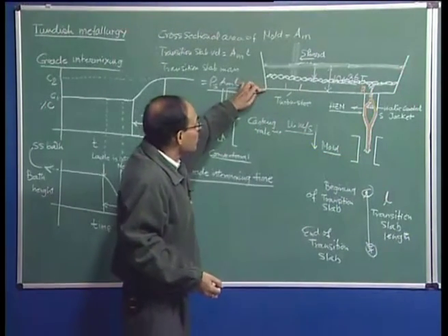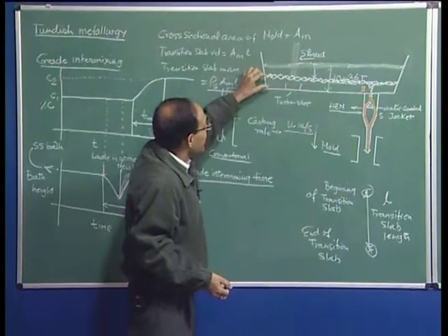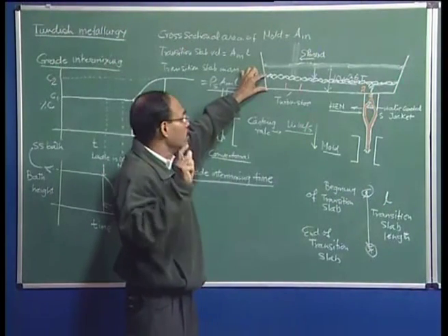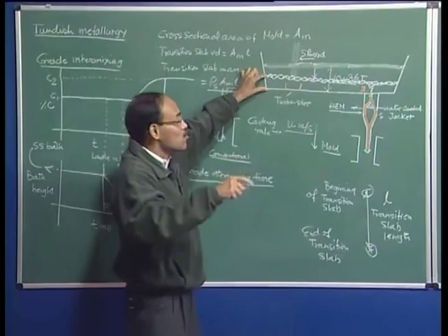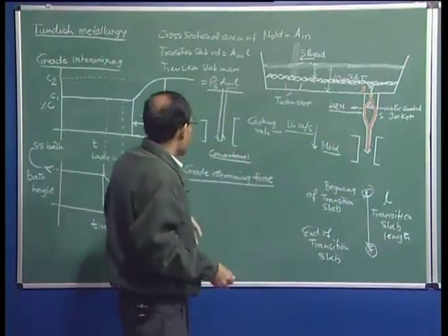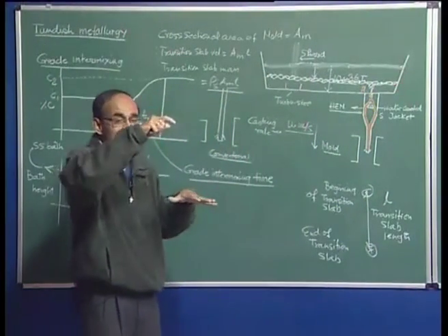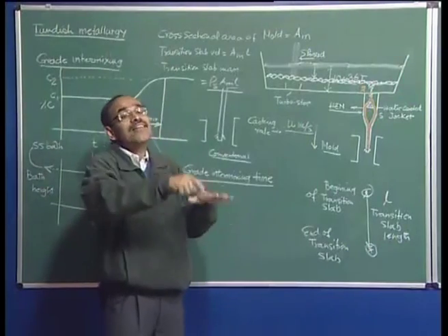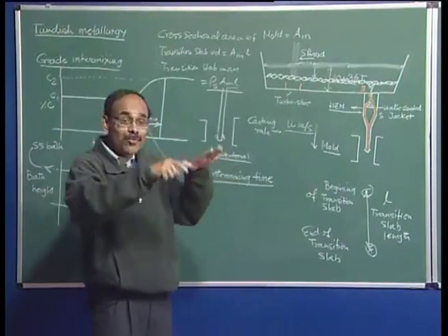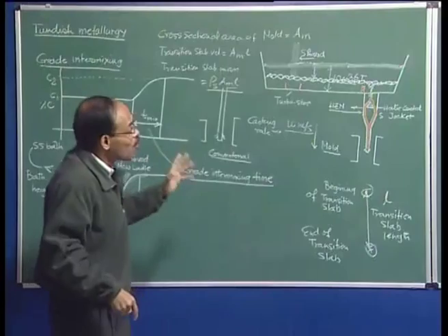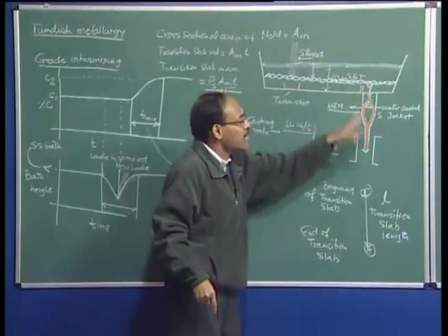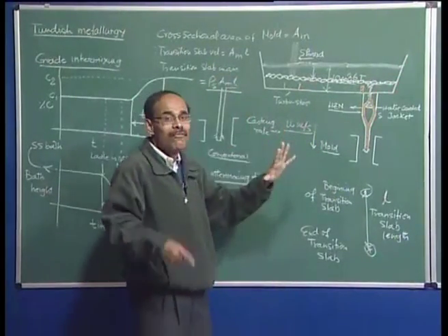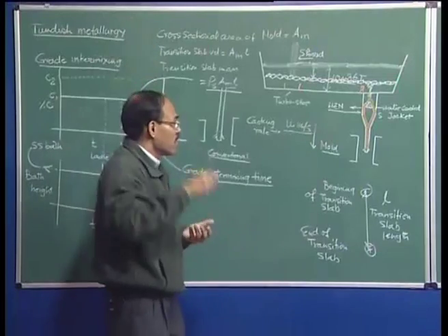As a result, we open the second ladle when the bath is at a comfortable level itself, but that again gives rise to a larger transition slab volume. So, the level of the liquid and the transition slab volume are to be optimized simultaneously. We do not like to have slag entrainment, and at the same time, we would not like to have a larger transition slab volume.